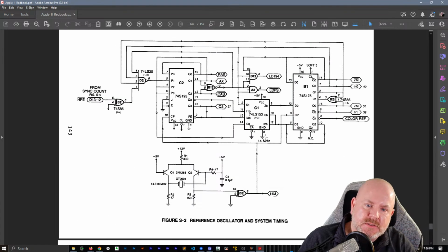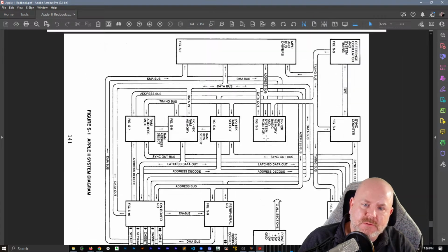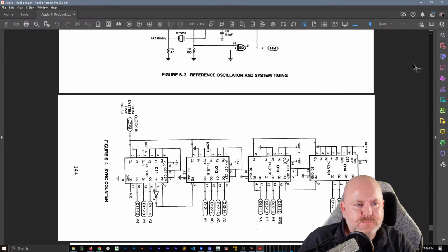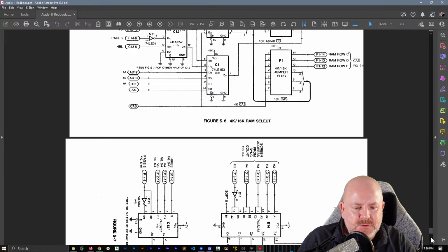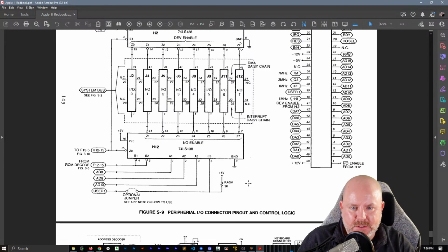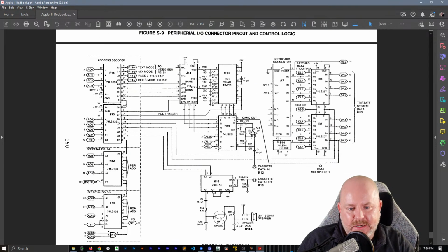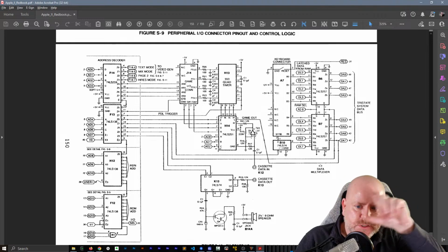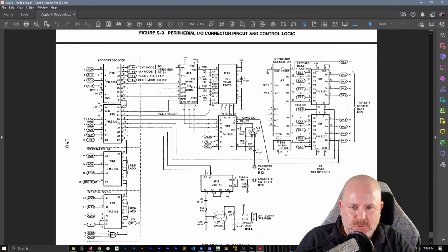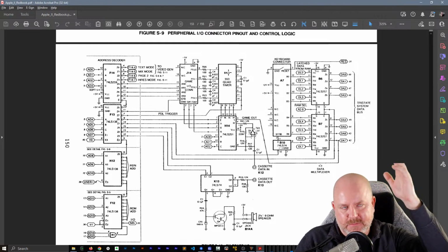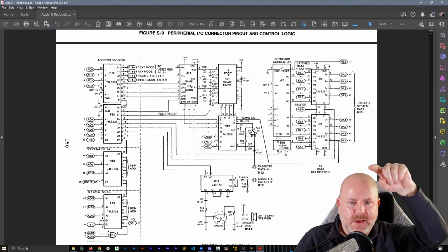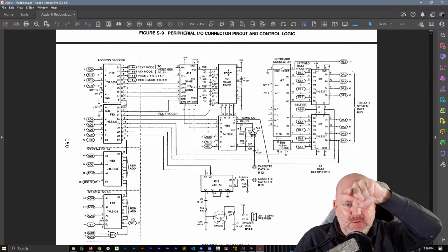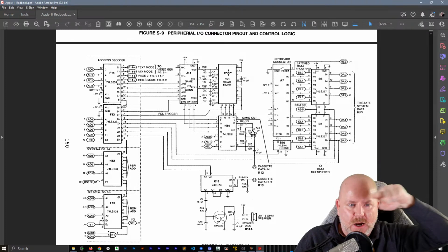That's D. C2. I'm just looking anywhere now. I mean, usually these gates are right next to each other because remember the IDs for these chips are the grid on the PCB. So H13 is, and I forget if it's column or row, but let's say row H, column 13.